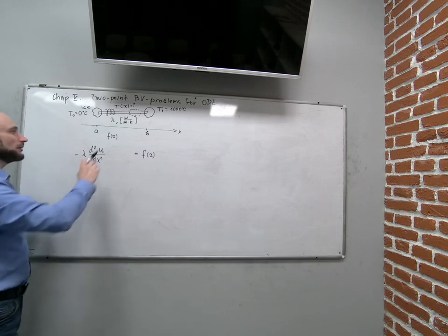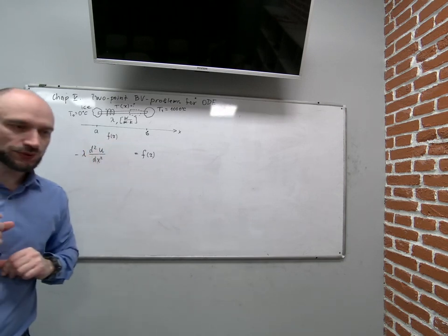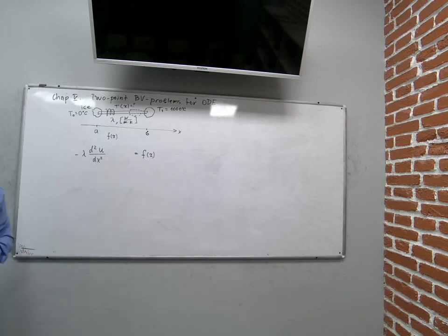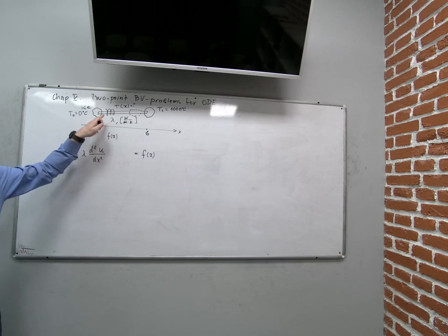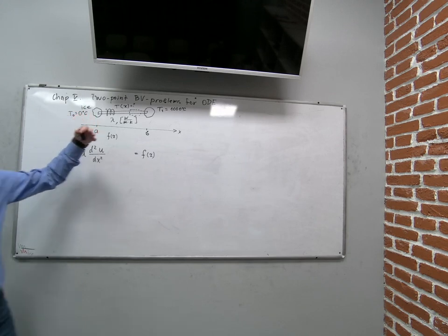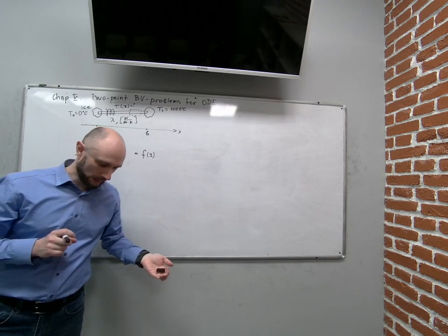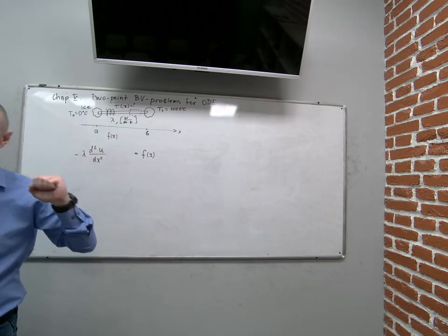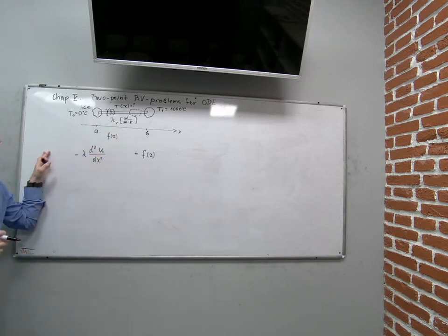What else? We can also imagine that this heat sink or heat source also depends on the temperature itself. The example of such behavior is some chemical process. If we have some chemical process occurring in the body of this rod, and in this process we have heat supply or heat sink, then this function may also depend on the temperature itself.